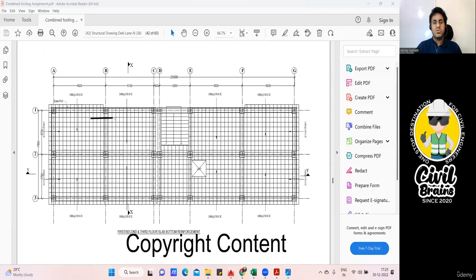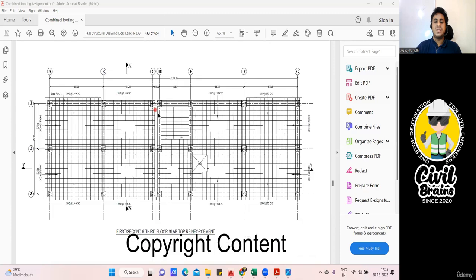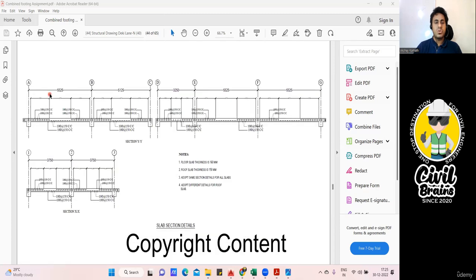Okay. This bar you want to find now. How you'll find? Very simple. Again, you have to go to the cross section where you need to check. At B grade, you check. They will give this section. This section will be shown. Check this section and tell me what is the diameter of the bar given. And then, again, the number of bar remains same because this length and this length is same. So number of bar remains the same. 48 only we will get. But only the thing is, come to the B section.